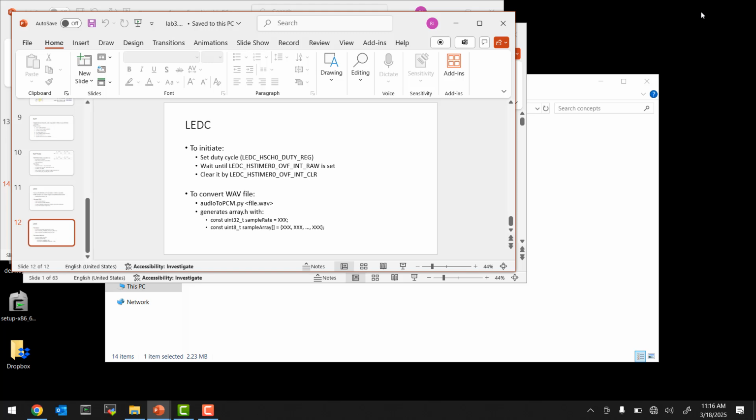And then divide that by the 5 levels, 5 LEDs, to rescale it to 5. That way, the audio will be on this logarithmic scale, because your ears hear audio intensity on a logarithmic scale, not a linear scale. So we want the audio visualizer to also be logarithmic, and that's all described in the lab sheet.